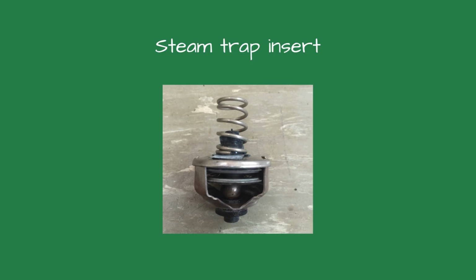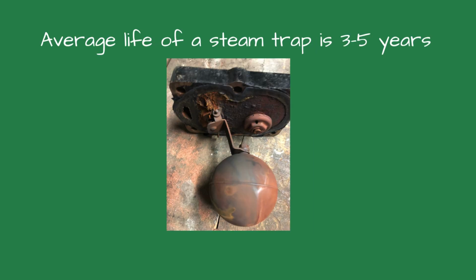With the labor involved in testing, I find it's easier and a lot less money to just replace the internal components, which pay for themselves. You can purchase steam trap inserts from a heating wholesaler. The average life of a steam trap is 3 to 5 years, but I've seen traps 3 to 5 decades old still working.